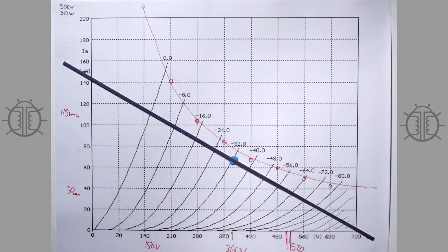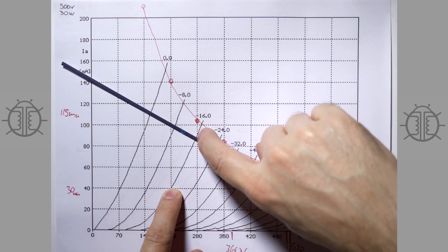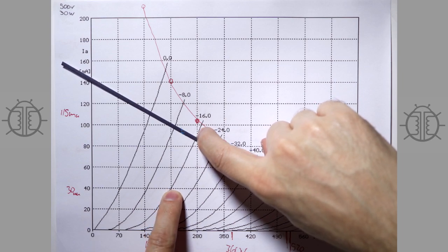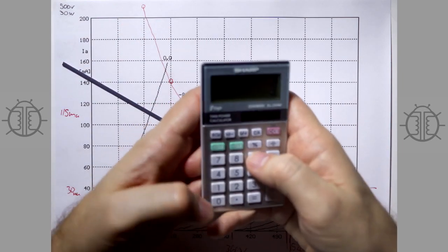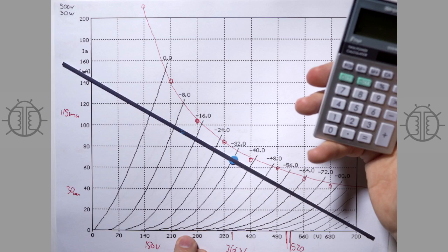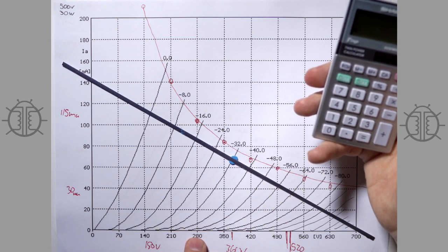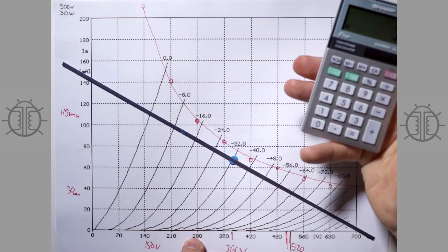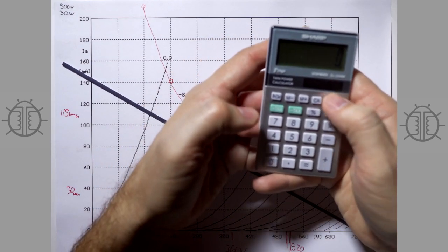You can also, this is interesting, like just with before, figure out the plate impedance of this stage just by looking at how much current you have to drop into the plate to change it by, let's say, it's changed even by 70 volts here, and you can see we're going from here to here. This is 90 minus 40, so, here we go. In order to change the plate by 90 volts, we have to put in 50 milliamps. So we're going to do 90 divided by 50.